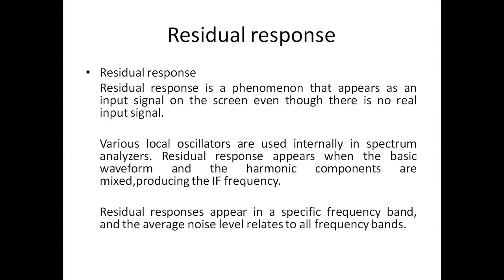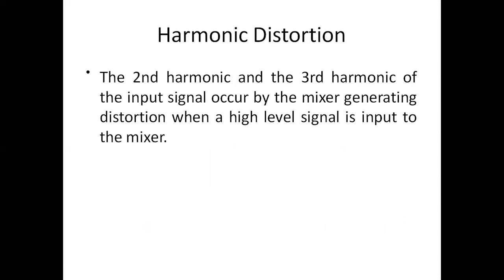So this residual response will appear when the basic waveform and the harmonic components are mixed, producing the IF frequency. These residual responses will appear in all frequency bands and in the average noise level. This residual response can't be completely eliminated since we are using oscillators.